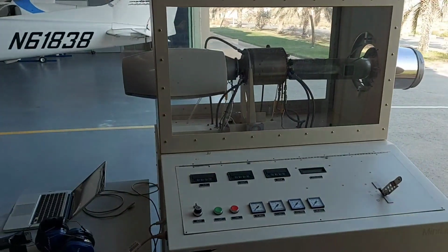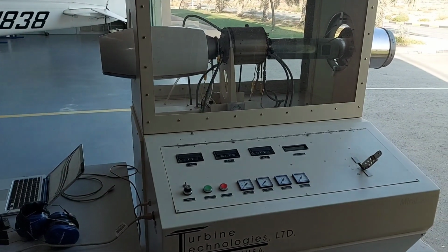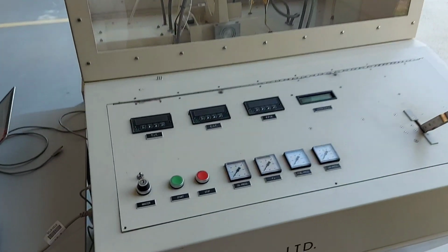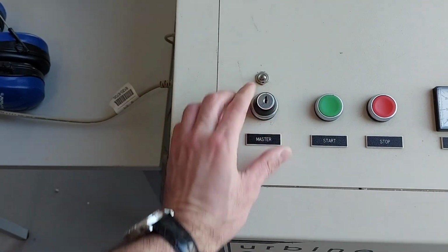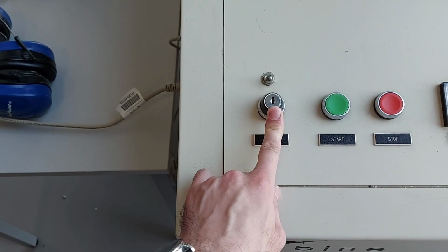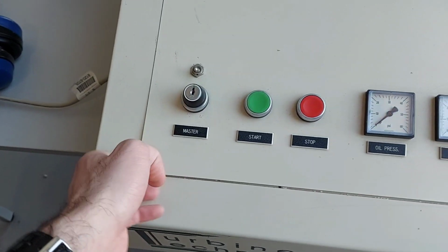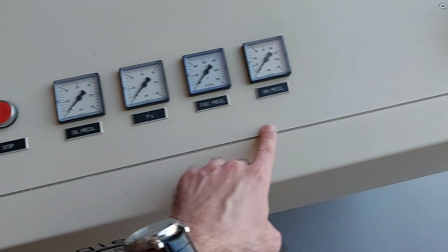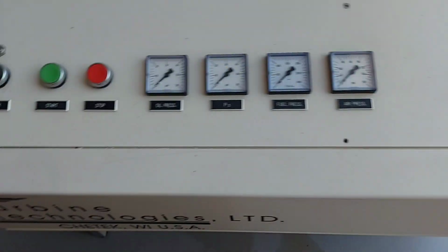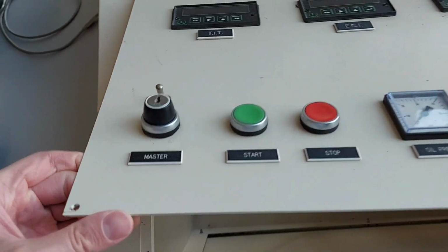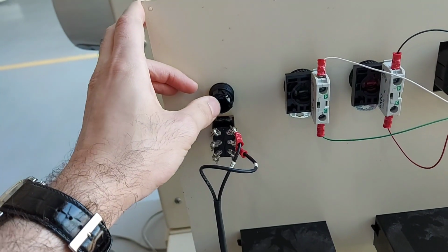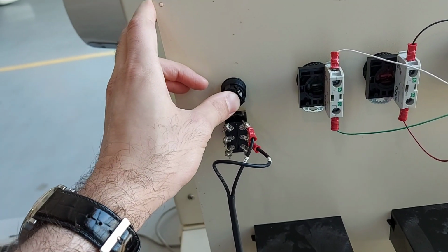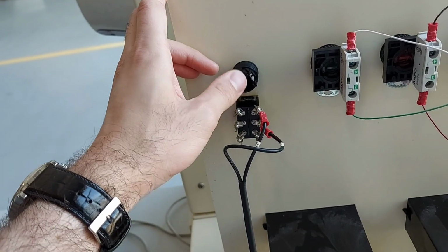Once the oil and the fuel have been put inside the simulator, most of the campuses will have the master switch here, but we don't have the key. So what we recommend is that you remove the 3 screws holding this panel down, and underneath this panel you can get access to the switch itself. Unplug it from the key, the lock, and you can put a manual switch.